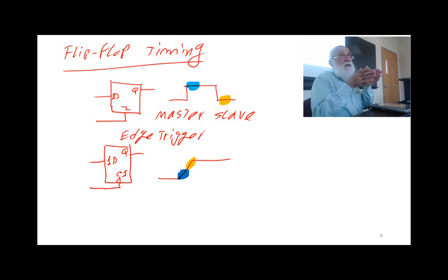Or, actually, I cannot change my input too close to clock rising or too close to clock changing. And after the clock has changed, again, I cannot change my data so quickly.